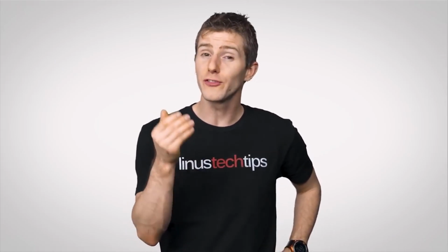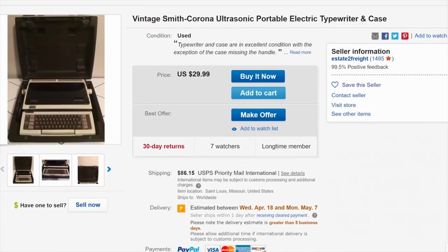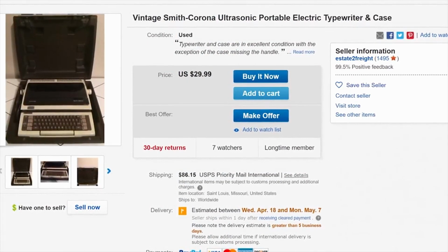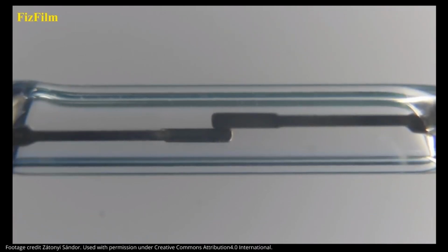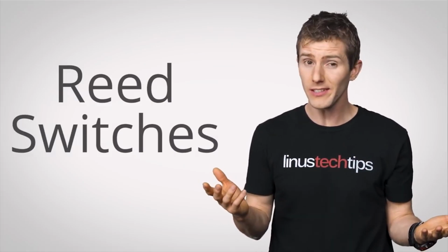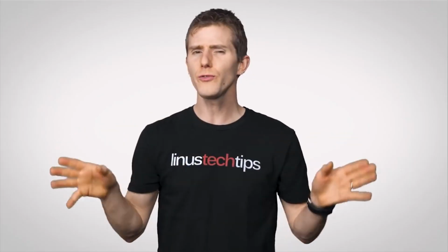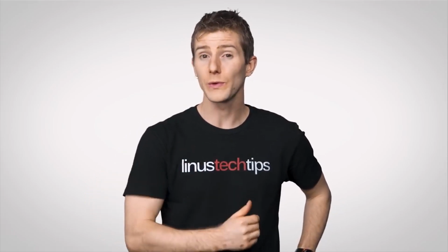Many early keyboards used key switches that were pretty different from what you're probably typing on right now, including ultrasonic switches that actually listened to the different vibration each key would make as it was pressed, and this one was a bit more common, ones that used magnets that got close to a pair of metal pieces, causing them to come into contact with each other whenever the key was pushed down. These were called reed switches. And while this concept is actually still in use today in applications like switching off a laptop when you close the lid, they proved to be too fragile and inaccurate for keyboards. So a couple of alternative designs quickly replaced reed switches.